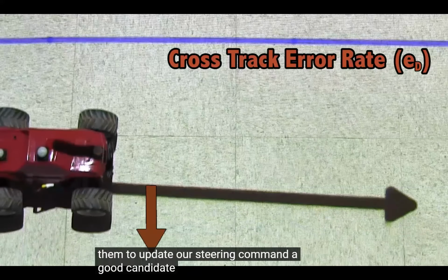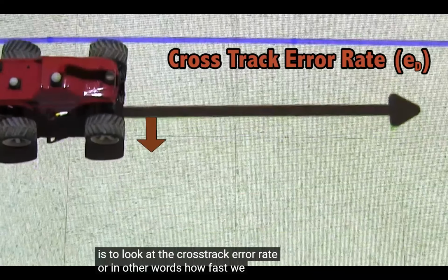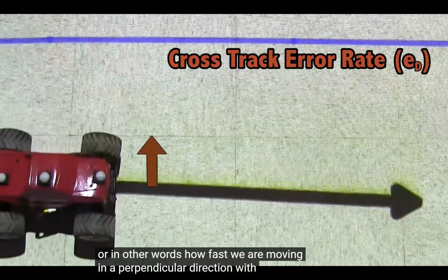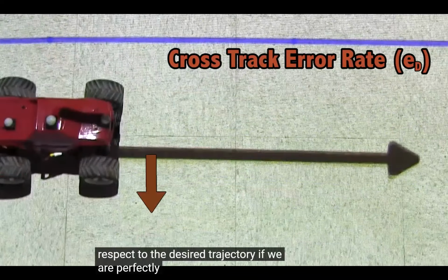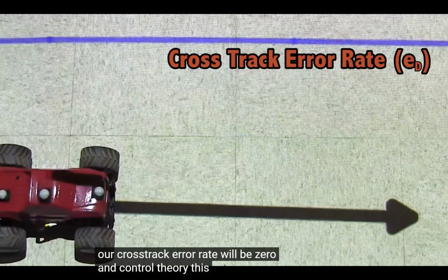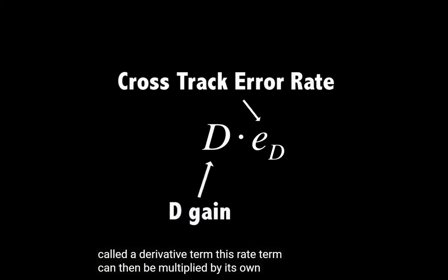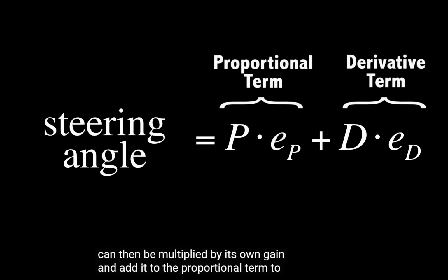A good candidate for an extra measurement is to look at the cross-track error rate, or in other words, how fast we are moving in a perpendicular direction with respect to the desired trajectory. If we are perfectly following the trajectory, our cross-track error rate will be 0. In control theory, this is what is called a derivative term. This rate term can then be multiplied by its own gain and added to the proportional term to construct an